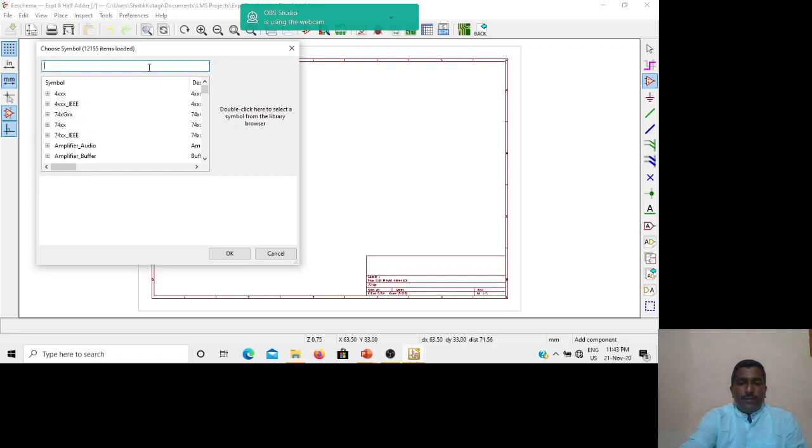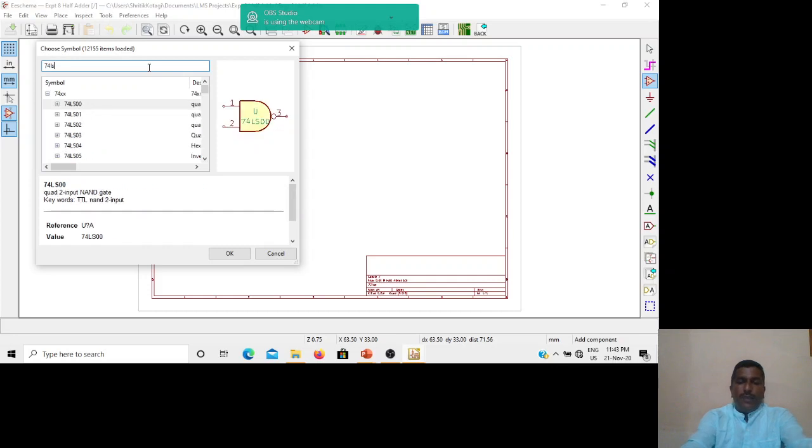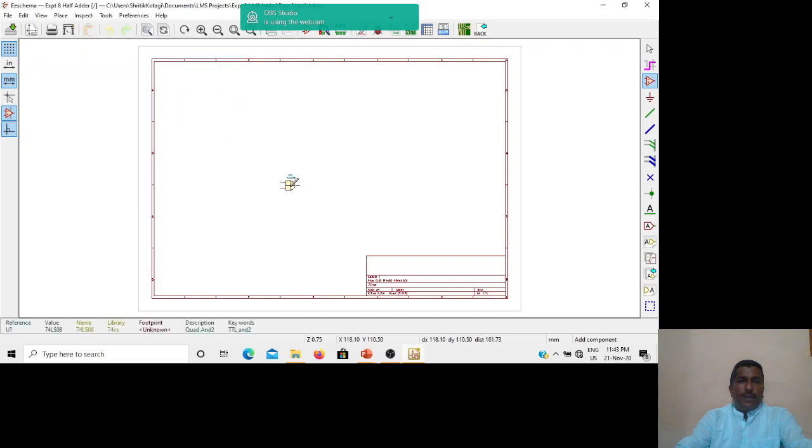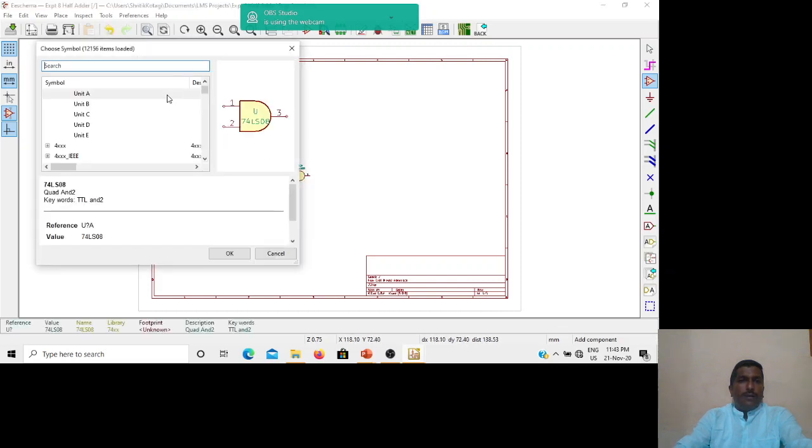I require 7408, 74LS08 for carry, and 74LS86 for sum.